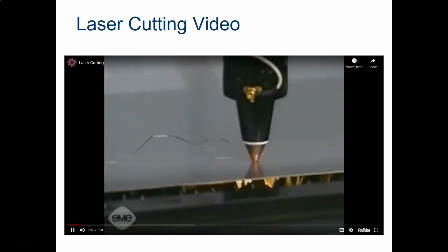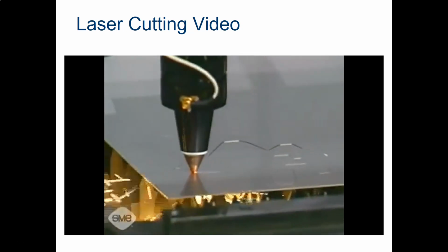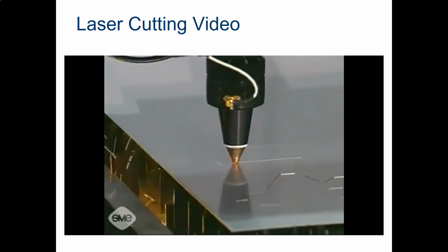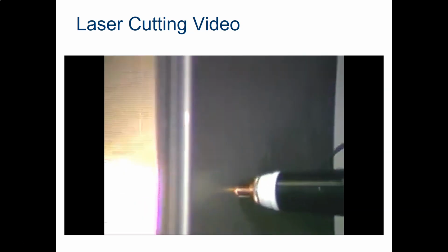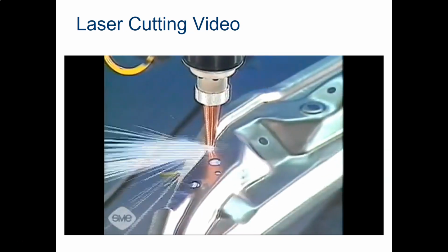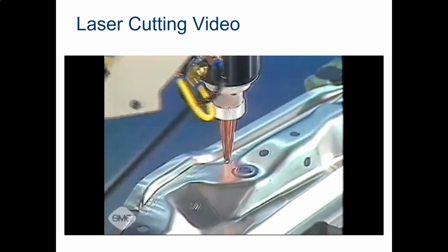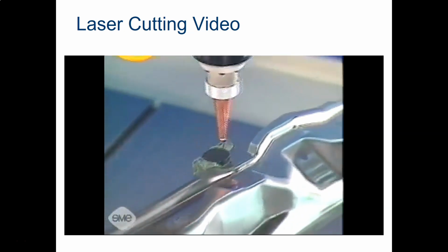Laser cutting uses a beam of laser light to generate heat for cutting metals and other materials. Laser's advantages over other thermal cutting processes include a narrower kerf, narrower heat-affected zone, and finer edge. Cuts achievable with a laser are smoother than with other thermal processes and may require no secondary edge finishing. Sheet metal may be contour cut rapidly, and small holes can be drilled in under a second.